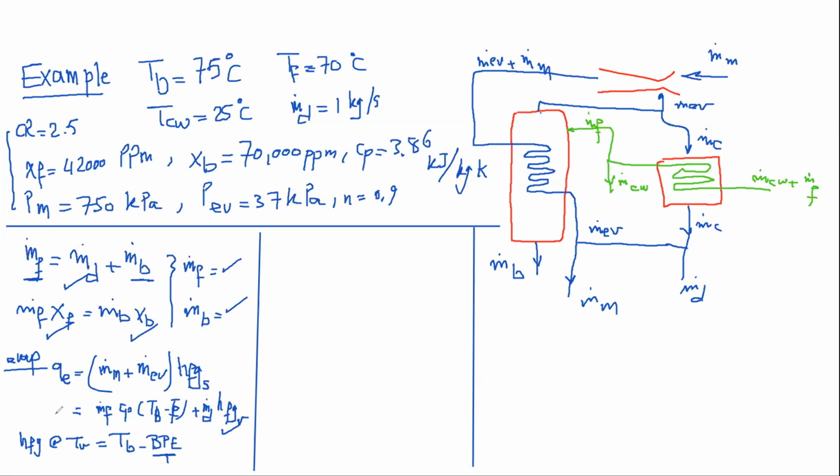Okay, fine. Now, Doctor, next thing to do: look at this equation. We don't know the temperature Ts. We need it. Why do we need it? Because we need to determine HFGS. So Ts is the saturation temperature at the pressure Ps. Do we have the pressure Ps? Yes, we should have it.